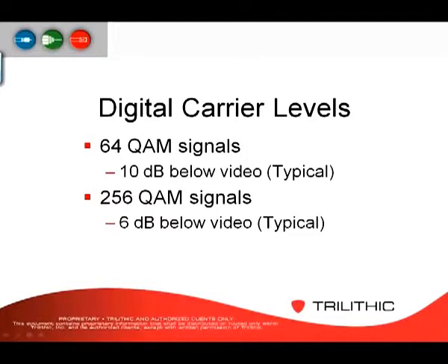Many operators set 64 QAM signals 10 dB below the video, and for 256 QAM, signals are set at 6 dB down from the actual video carriers.